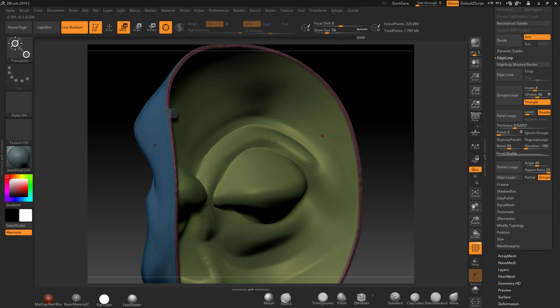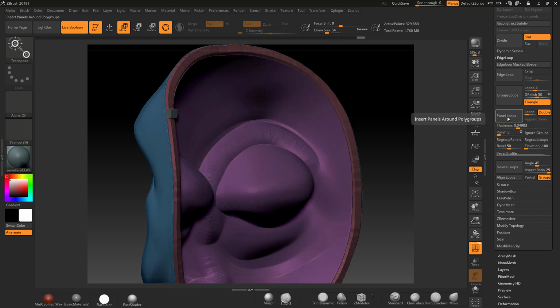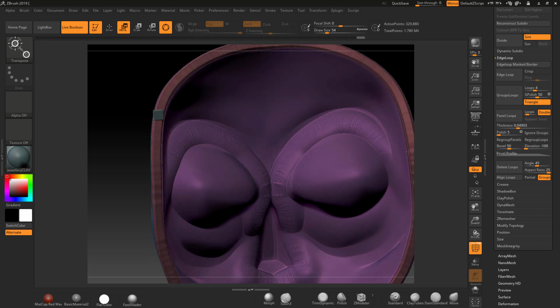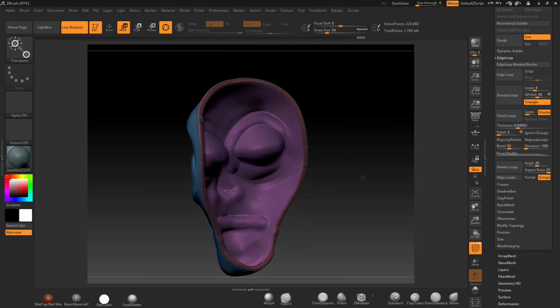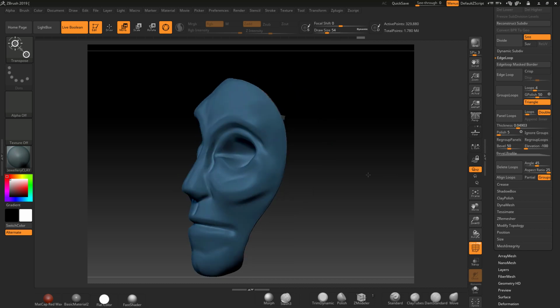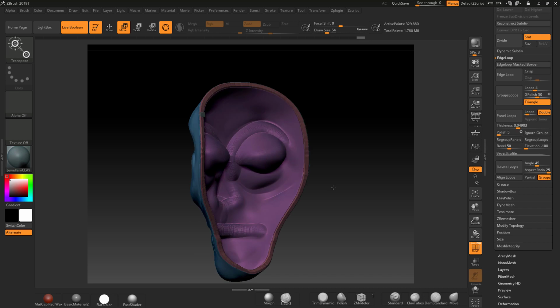and we've got this. It's not good enough. Control Z to go back. Let's take our thickness and make it a little bit thicker. That's pretty good. Yep, that's pretty much 2 millimeters. So there we go, we've created that. So you've created that on the inside, it hasn't destroyed that. So I'm happy with that.